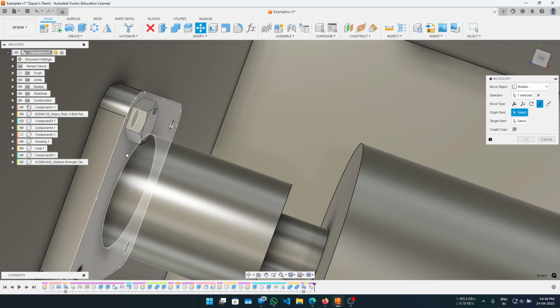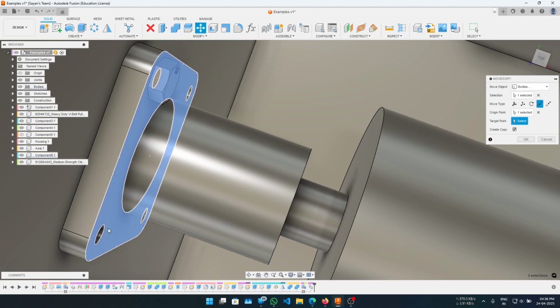So you see that when I hovered over this surface, I can see the correct circle. But when I go to select that surface, some other surface is getting selected. So when I see the circle, I press Control and then I can select this. Similar way, select that.